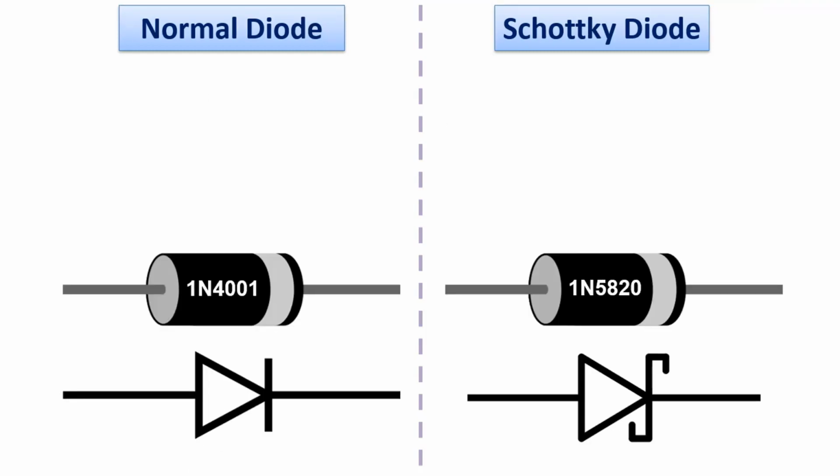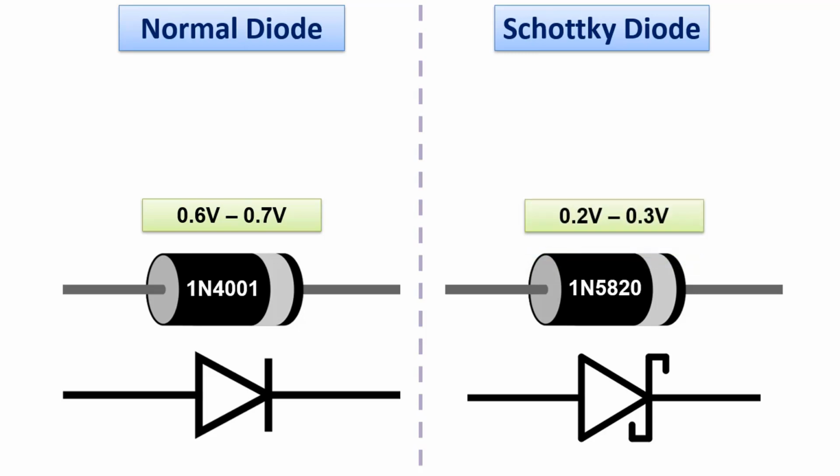There is a normal p-n-shaped diode made of silicon on the left, and a Schottky diode formed as a metal and semiconductor on the right. A voltage between about 0.6 volts and 0.7 volts is needed for the normal diode made of silicon on the left to conduct, while a voltage between 0.2 volts and 0.3 volts is sufficient for the Schottky diode, which is made up of a metal and semiconductor combination, to conduct.